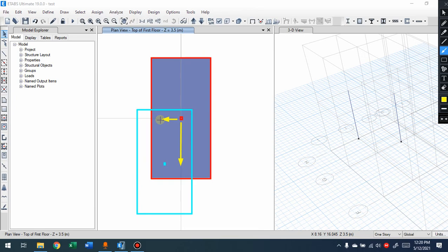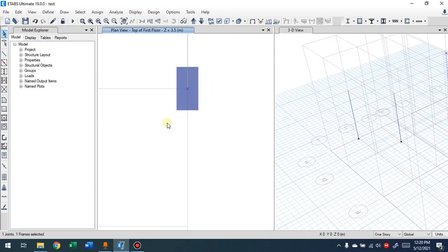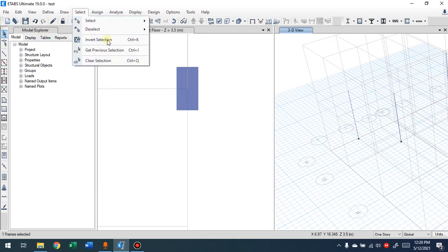Well, in order to do the movement, what do we have to do? Well, we select the column. Now selection in ETABS, we have two. This is whether cutting it or putting all of it inside, in two directions, selecting this one here. If the object is not completely within the selection here, it will not be selected. In the plan here, you can simply click on it. It will select like this. One click will select it. Escape will deselect it. I'll talk about selections in more detail. I'll come back to them because we have a lot of options there for selection that you need to know.